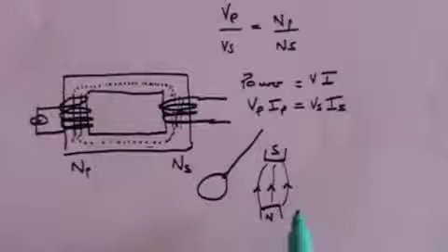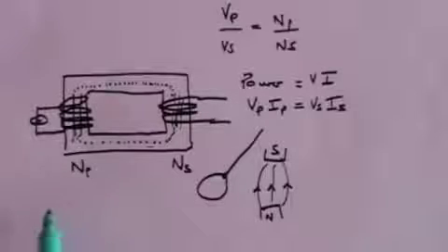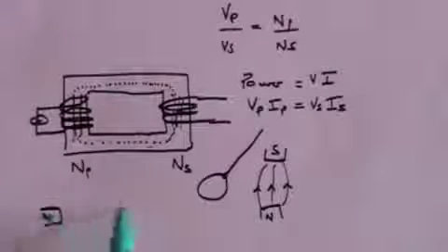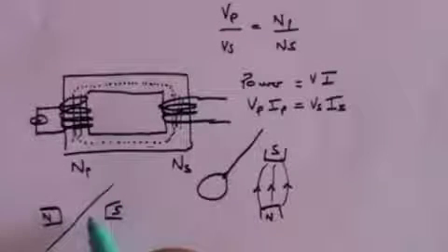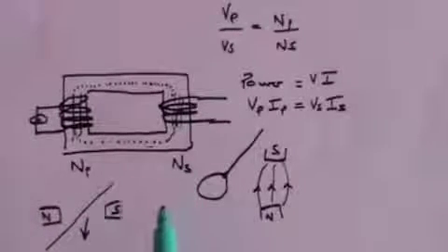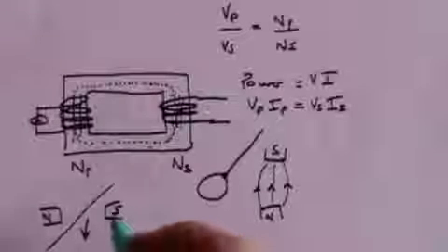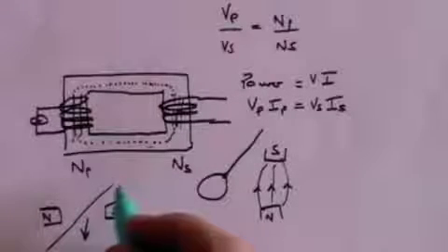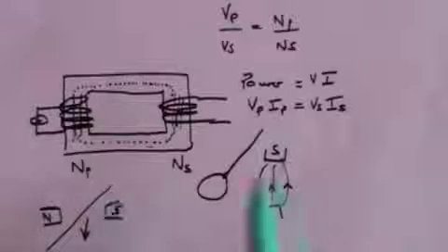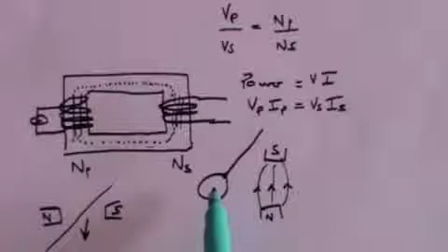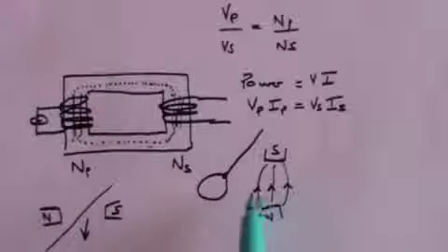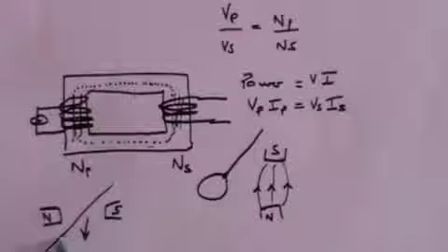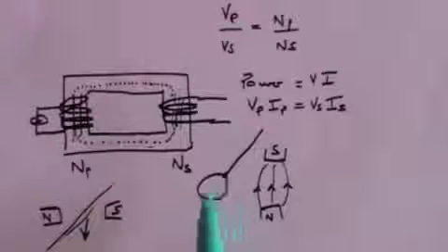Well, imagine it was a wire. We know that if you have a magnet, north-south, and here's a wire, if you move that wire down quickly, that will induce a current to flow in the wire. Well, exactly the same thing happens here. As the metallic disc goes through the magnetic field, it will induce a current. But unlike a wire, where the current flows along the wire, this is a metal disc.